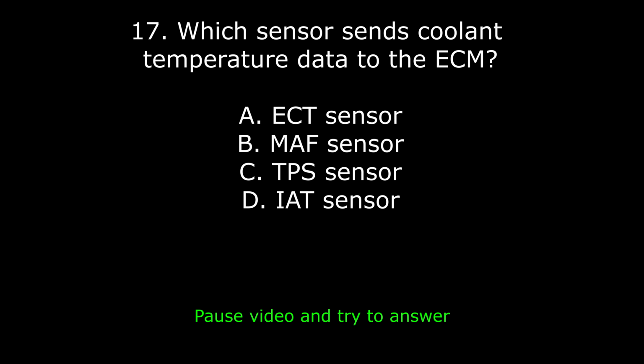18. When replacing a front fender equipped with side airbag sensors, what must be done? A. Replace all sensors. B. Disable SRS system and follow OEM procedures. C. Unplug battery only. D. Ground the sensors. Answer: B. Disable SRS system and follow OEM procedures. Airbag circuits must be powered down to prevent deployment during service.